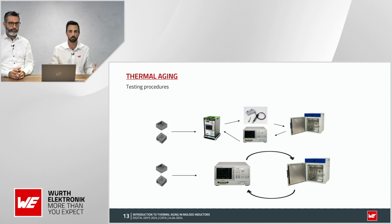This is a very nice procedure because you have the exact measurement of the increase of the AC losses, but you have two big problems. It is very time consuming, and also the parts must be soldered on PCBs, so the PCB will degrade. Another way to characterize this degradation process would be to find some electrical characteristic that would be easy to measure in the components, so we can do it in a fast way, and that is related to the AC losses in the core.